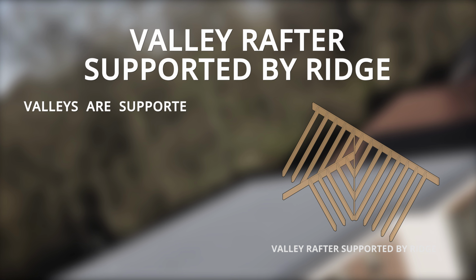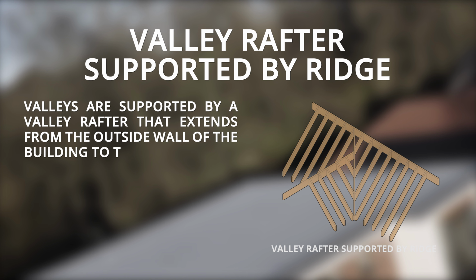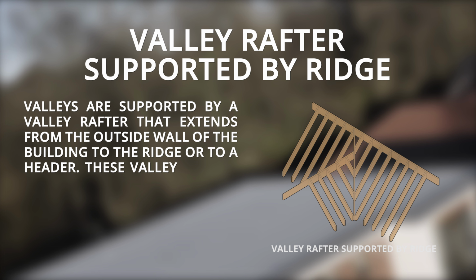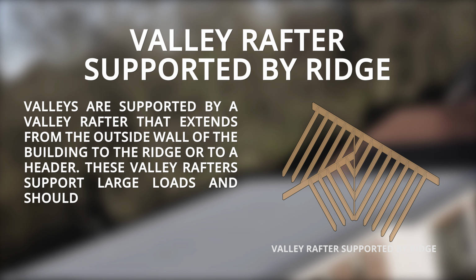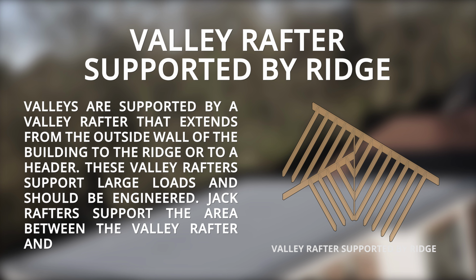Valley rafter supported by ridge. Valleys are supported by a valley rafter that extends from the outside wall of the building to the ridge or to a header. These valley rafters support large loads and should be engineered. Jack rafters support the area between the valley rafter and the ridge or header.